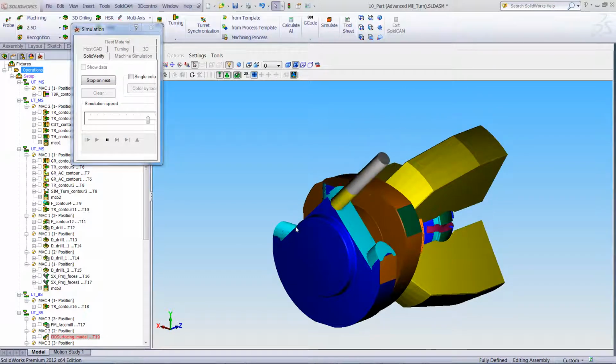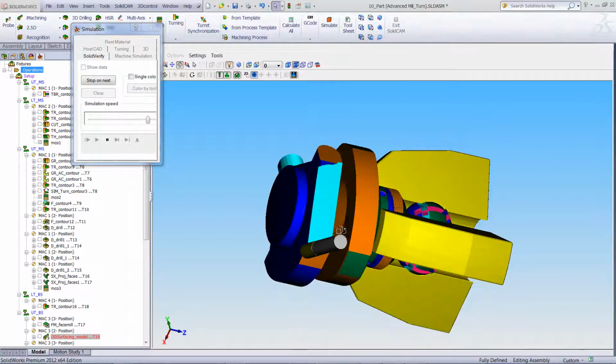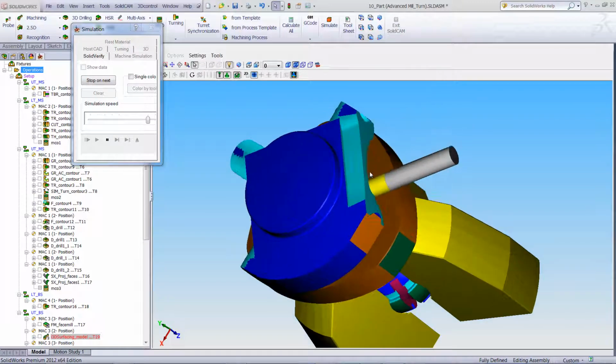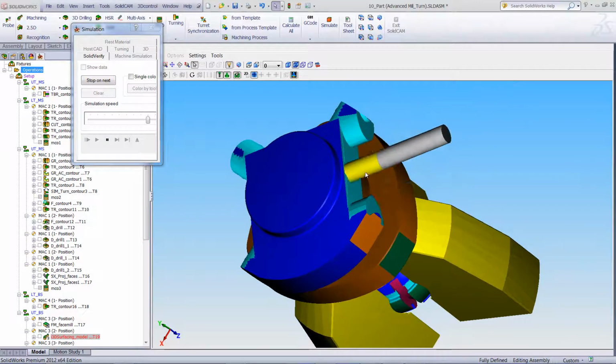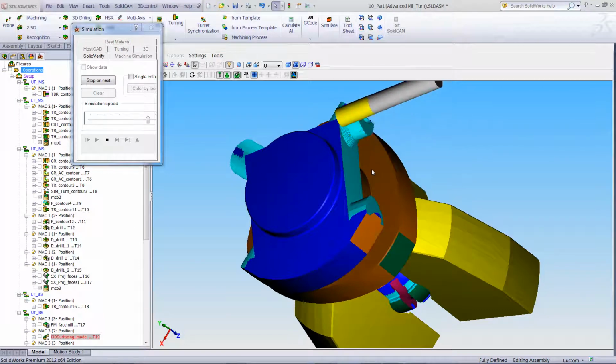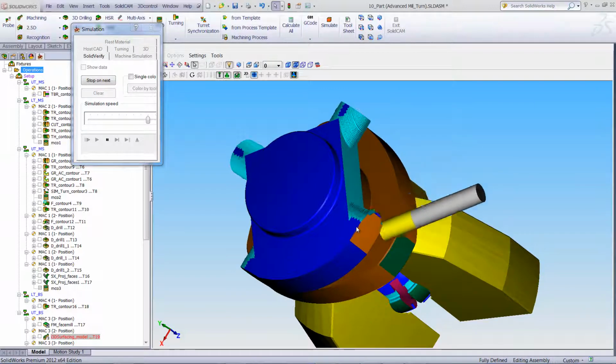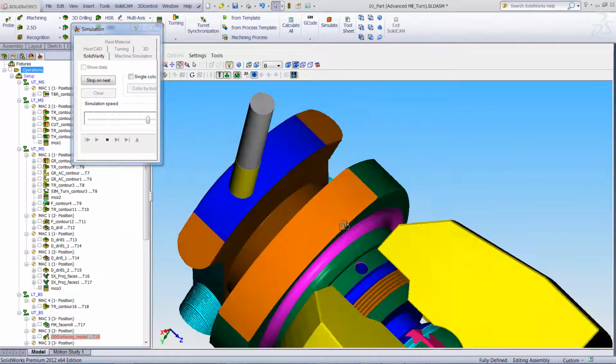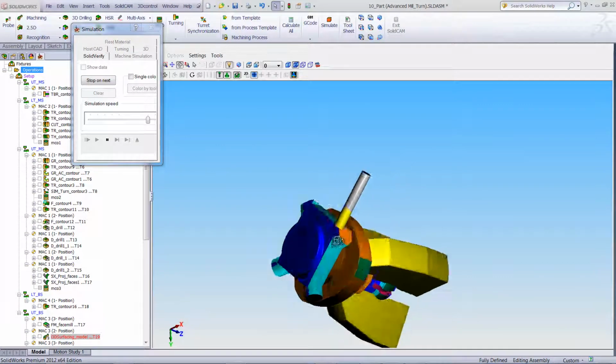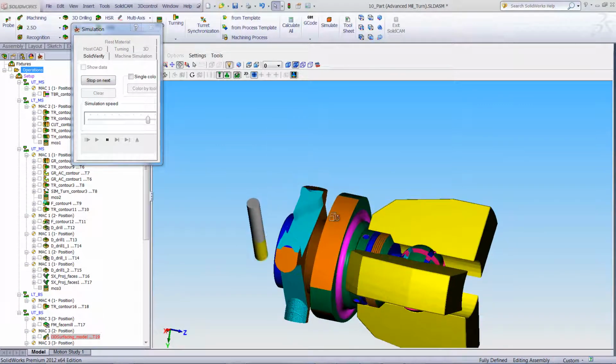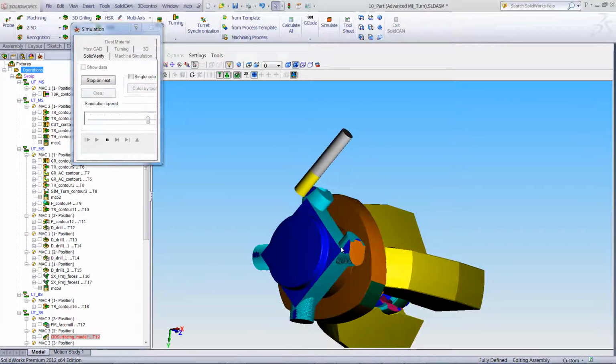This is just a copy of this area over here, indexed to the other side, and this will be done 4 times altogether, completing all 4 sides of the back part over here. And you can see the I machining is working actually very well in this area as well. Working now up, doing the rest machining on these studs over here. And now finishing off, going to this back area over here, completing the 4th side of this part as shown over here.